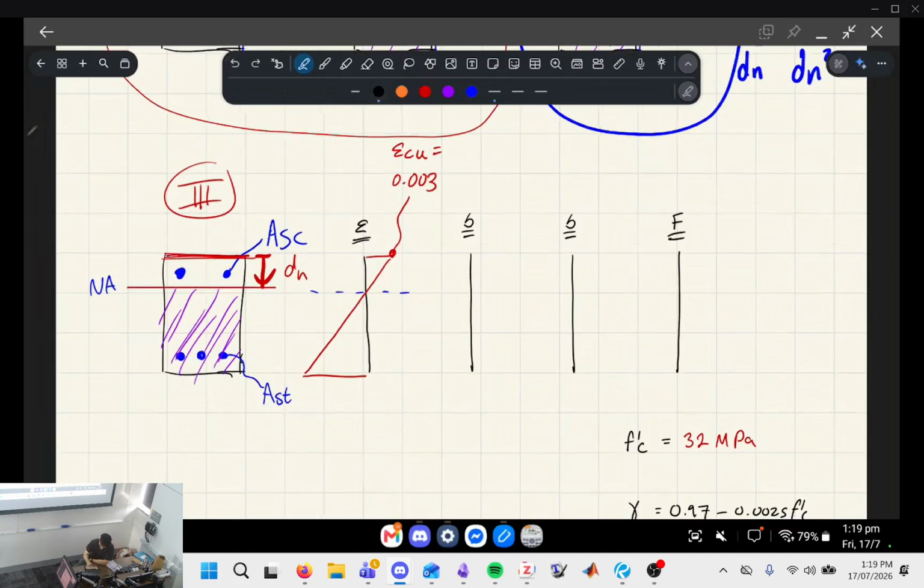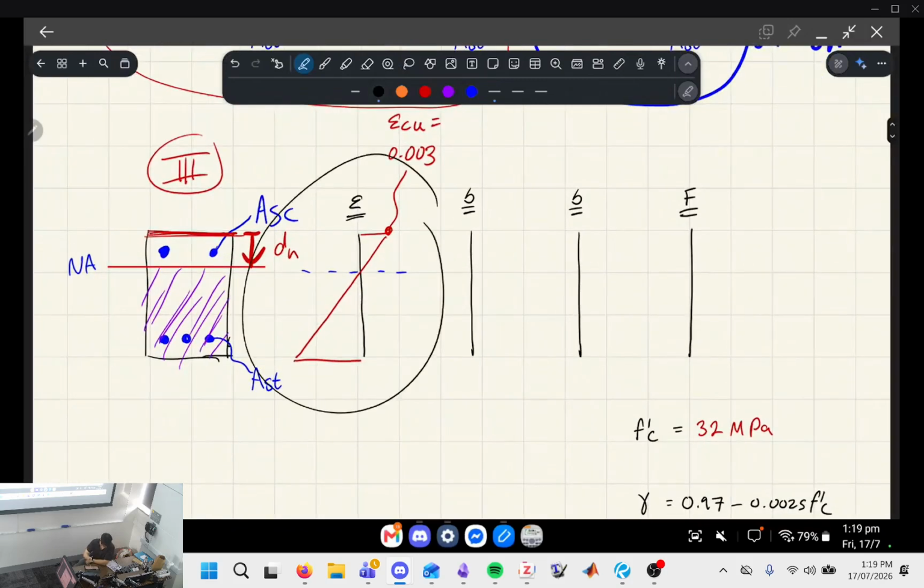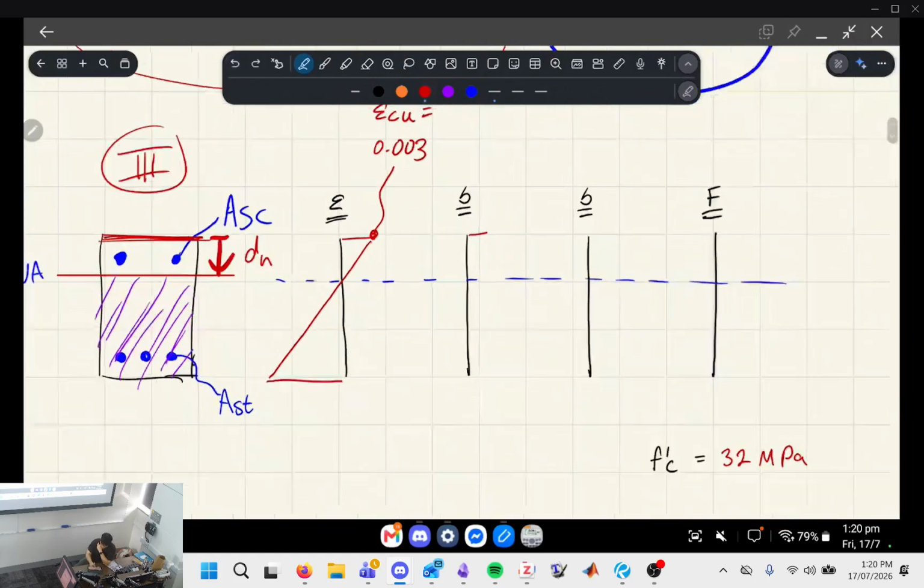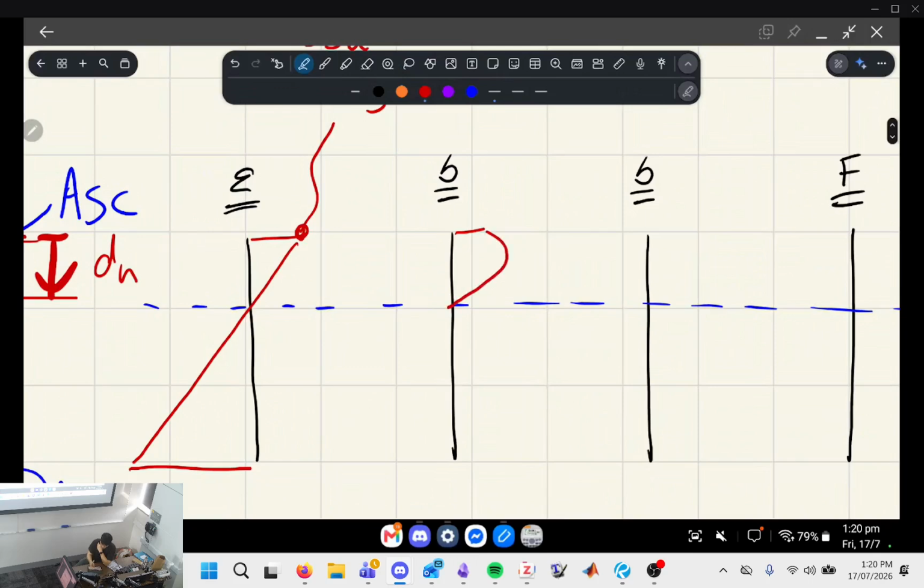Okay. So now we've got 2 points along this linear strain distribution, which we can do stuff with later. This neutral axis is going to extend across all of these graphs, because we're going to be graphing everything versus the depth. Essentially, how the concrete distribution for stress actually looks is like this, okay? So I'm drawing a parabola.